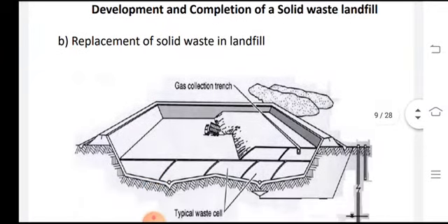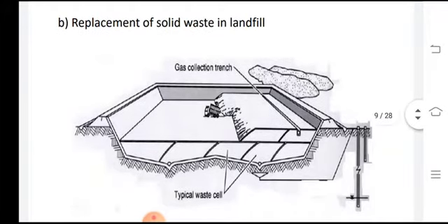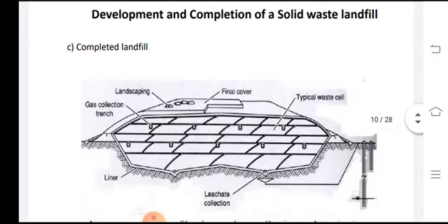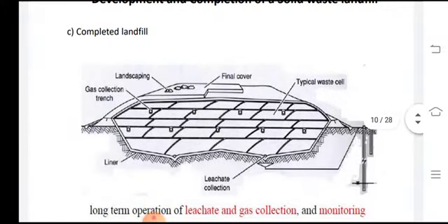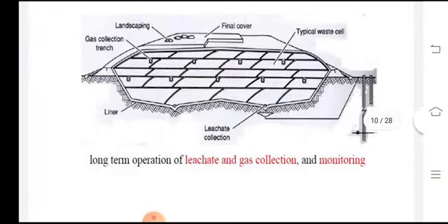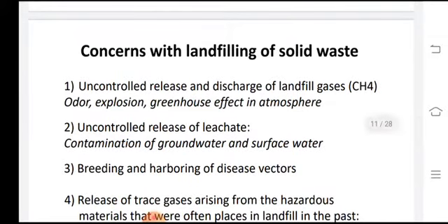Then you can see here the placement of solid waste in the landfill. It is being added and then it is being covered. Here it is development and completion of the landfill, and the completed landfill will look like this, in which the final cover has been provided and the landscaping has also been done to reduce the negative impact. And then long-term operation of the leachate and gas collection and monitoring will be available, so that the monitoring is continuously done. So what are the concerns with the landfilling of solid waste?